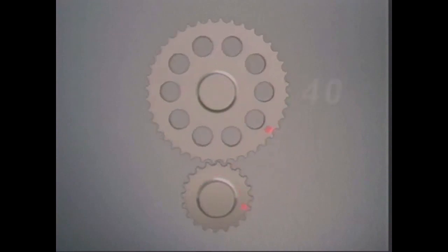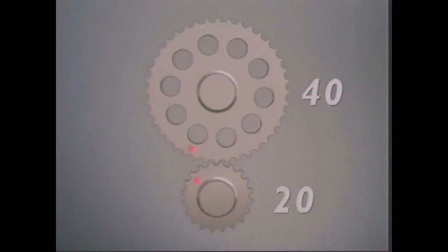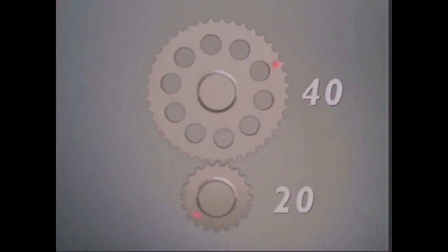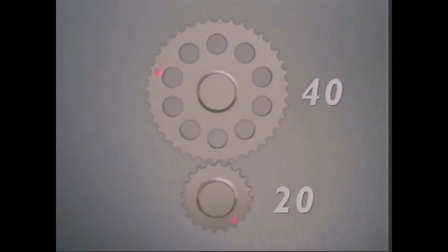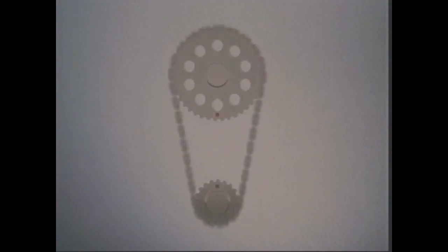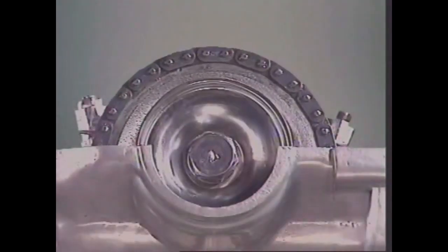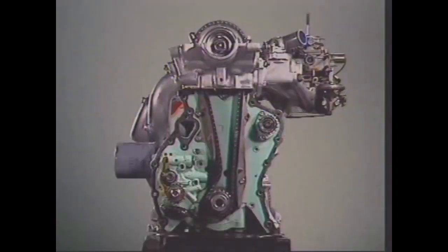One way to do this is with gears. One of these gears has 40 teeth and the other, the driving gear, has 20. When they mesh, the larger one rotates at half the speed of the smaller. If these gears are separated but linked with a chain, it makes them turn in the same direction, but they still turn at their same speeds. If the smaller gear is on the crankshaft and the other is on the camshaft, how fast does the camshaft turn compared with the crankshaft? Half the speed, just what the system needs.